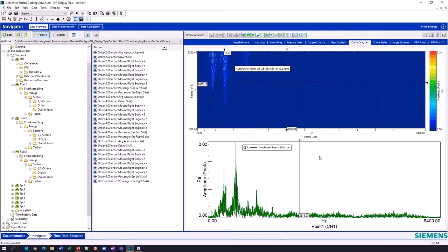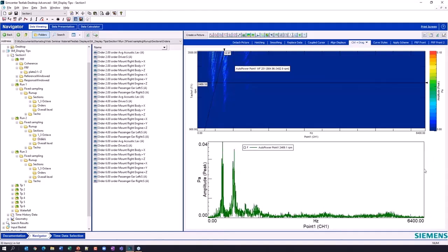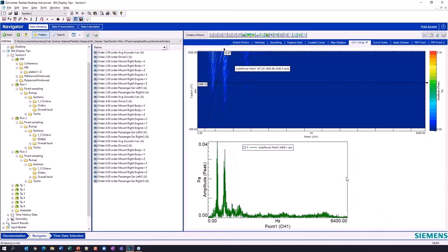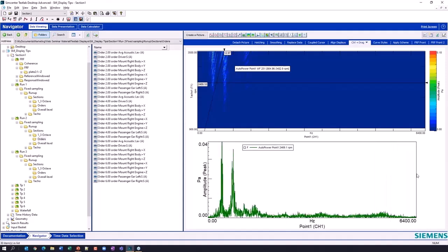But just graphically, again, I'm going in front of Pete's boss, and I don't want to have him trying to do that mental gymnastics while I'm presenting. So I'm just going to align these displays myself. Because this color map has this color scale over here, this guy isn't quite as wide as the guy in the bottom. So I'm going to come over here to the edge of this guy, and I'm going to hold the control key, and I'm going to hold that down. And if I now move this axis, I can now resize this display however I want. Okay, so I'm just going to artificially create some white space over here.